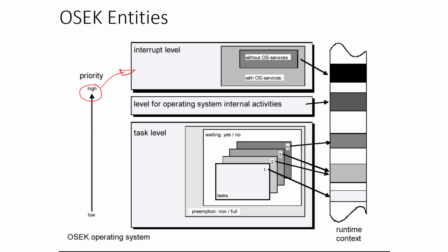All of those are what is required, in the sense like QNX. We mainly have to be reactive, in the sense an event happens and we react to it. That is where we will run many of these small processes with different levels of OS involvement. The OS, of course, will be there, so it will run at a slightly lower priority than the interrupt processing. Interrupt processing has the highest priority, and then a bunch of user level tasks where different levels of preemptibility will be supported.